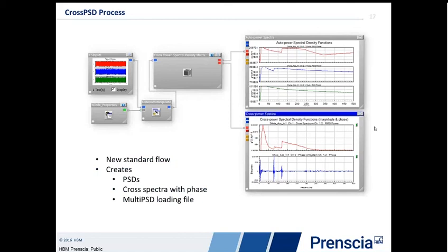To capture the cross-correlation information, this is basically how one load input interacts with another, I actually have to start with a time series because it's the time series data that had this phasing information. So it brings in the time series information, and then it'll generate a PSD for each time series. It'll generate cross-correlation matrices for each pair of inputs.